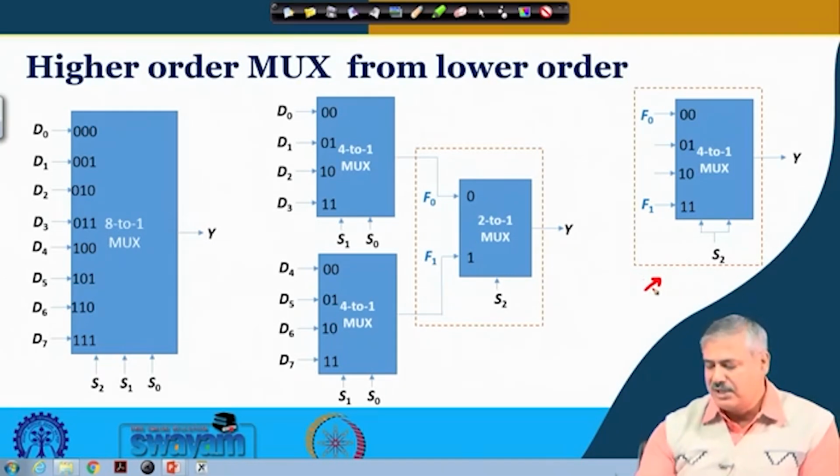What we are doing? So, there are 2 select inputs, we just have made common. So, S2 is connected over here. So, whenever we place 0, both the select inputs become 0. Okay. So, this will be selected, and when we place 1, these 2 become 1. So, one of these will be selected. So, either this gets selected or this gets selected, right.